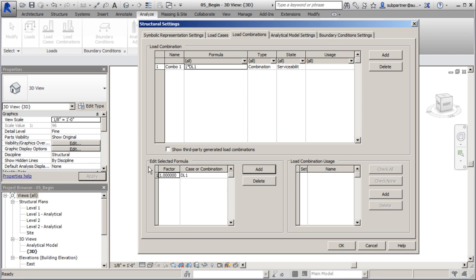And what this does is it basically allows you to take a fraction of a load or each load within your combination and apply a factor to it, a percentage factor. So for instance, in our case here, let's say we wanted to create a load combination of the dead load of the object, its own weight, but I also want to add another thing into that combination. Let's say, from 0 to 1, you have to put in a factor. Let's say 0.75. I can also drop in maybe my temporary load. Actually, we'll do snow load, just as a little example here. So that's how we get that done.